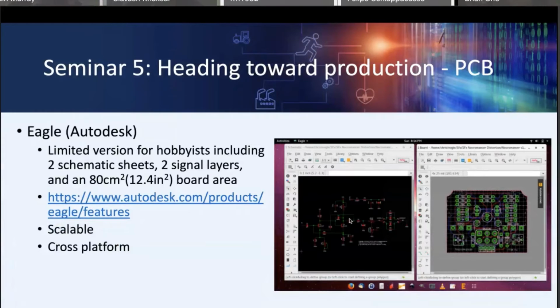For example, it's only a two layer board. So you can have a layer on the top of the board and a layer on the bottom of the board. That's it. Quite often what you want to do is have more layers on the board for things like ground planes to reduce noise. Maybe it's a complex or very dense pitch on the circuits themselves, so lots of pins in a given area. So you'll need to have multiple layers, and you need to move to something a little bit better.